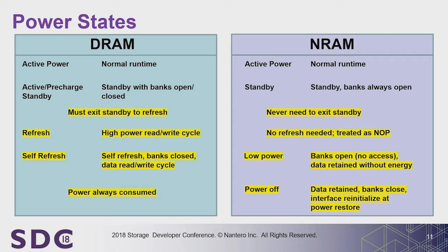And then it also does some other magic stuff about normalizing voltages on lines and stuff like that. But the main function is that writing back of the array. But I said we have a non-destructive read. We don't need precharge at all. And in fact, we no-op it when a controller sends us a precharge command because there's nothing to do. The data is still there.